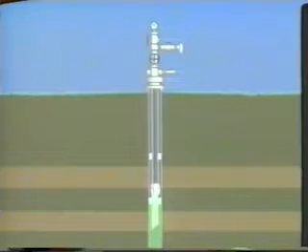Plugs that hold pressure from both directions are designed to be used to isolate and separate two producing zones in a well. In such a situation, the pressure differential could be from either direction and could change as one zone is produced. Therefore, the plug used to separate two zones must be able to hold pressure from both directions to assure that the zones remain isolated.